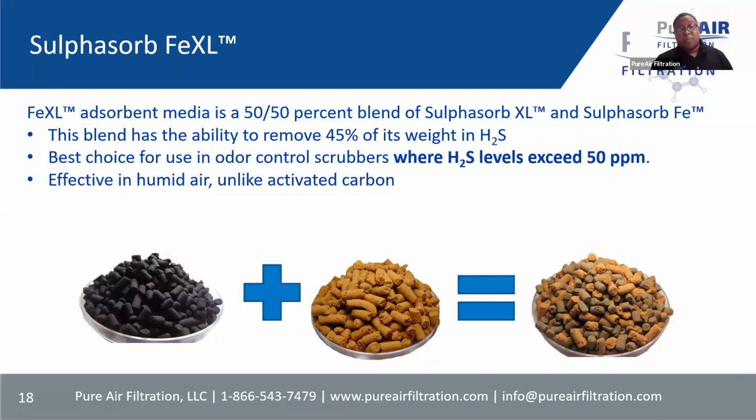Again, this is recommended simply because in wastewater treatment plant applications, that humidity, those water vapor molecules, are going to be treated as a competing molecule. Whereas activated carbon will just get saturated with the water molecules, the Sulfazorb FE is actually going to be able to use that to its benefit to help facilitate that chemical change between the H₂S and the media.